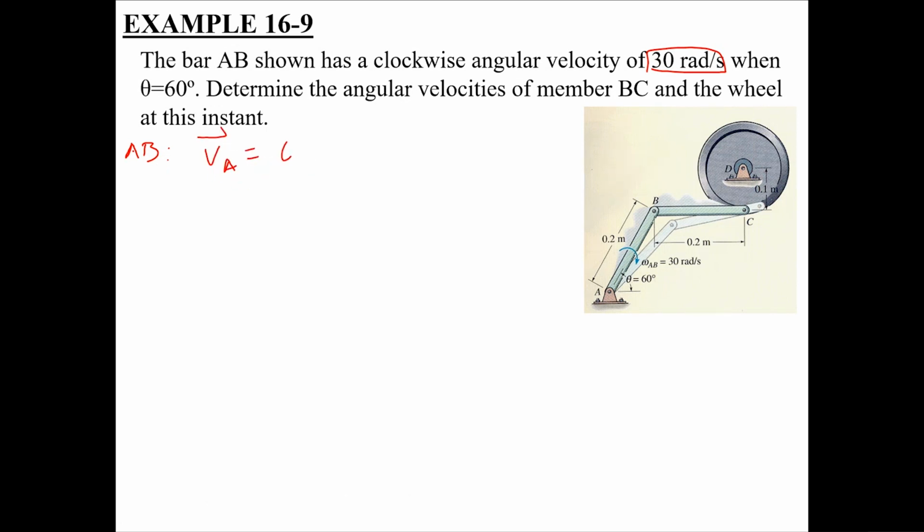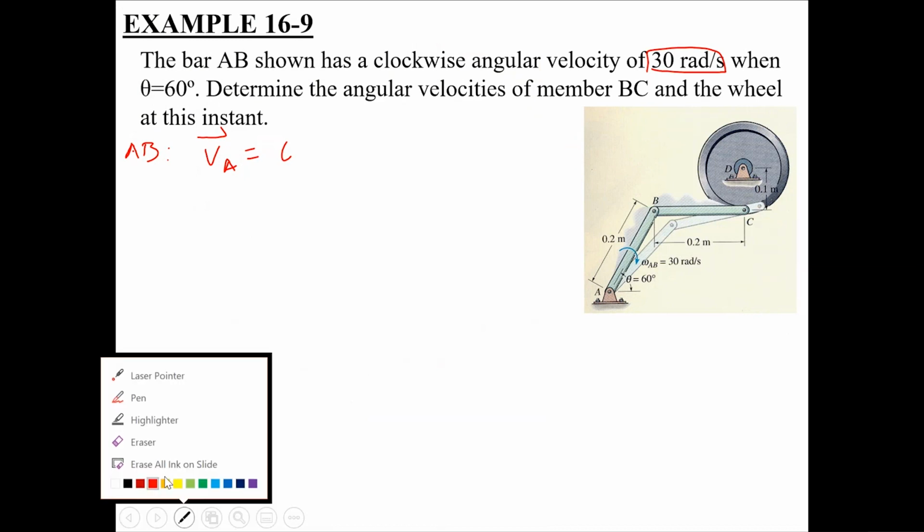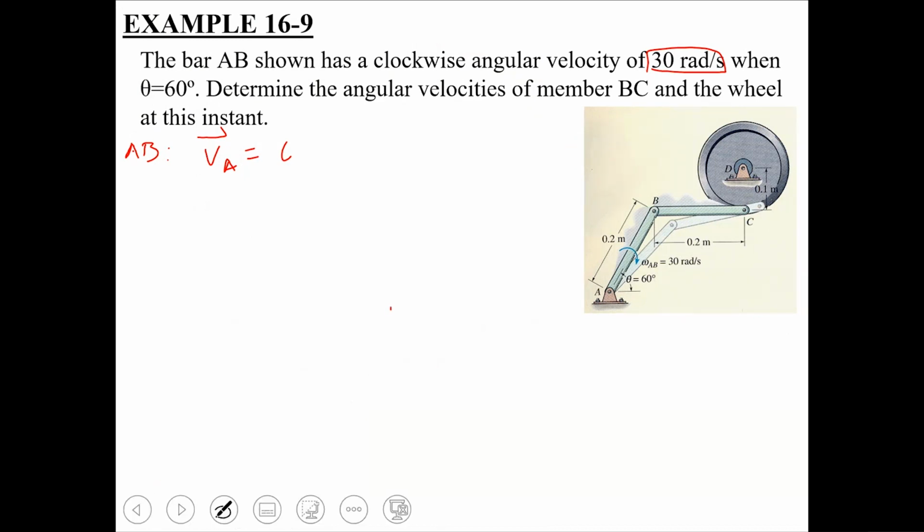It is going to be omega cross R. This is going to be omega cross R, but what should be the omega? It is omega AB cross RB. So what is omega AB? Sir, this is given as -30k radians per second. The way we just discussed, we are going to take it as -30k. Here, do not go by the assumption that omega must always be assumed counter clockwise. Yes, it is fine as an assumption, but here you have been given a value, so try to use it in its correct sense.